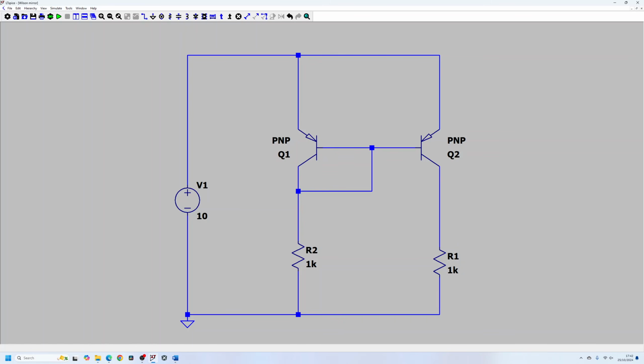So the advantage of a basic current mirror is that it's widely used, obviously, and it needs one less transistor than the current mirror that I'm going to talk about next, the Wilson mirror. Obviously, you can see the circuit is quite simple. It's very easy to understand. You can see what's going on. You only need 2 transistors and 1 resistor to build up a current source, basically.